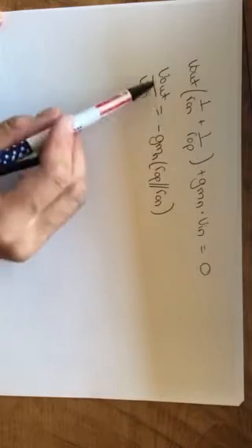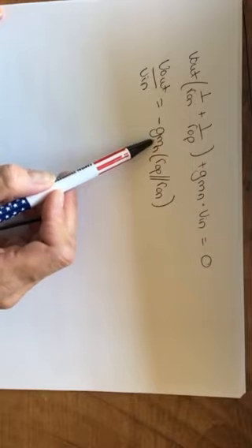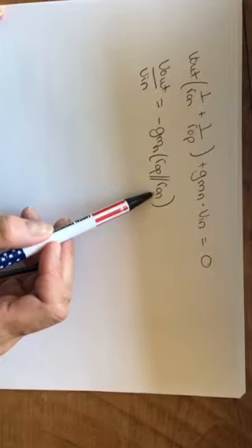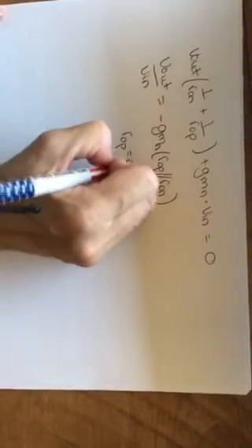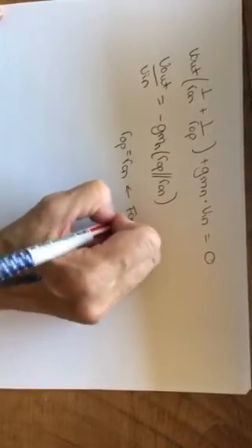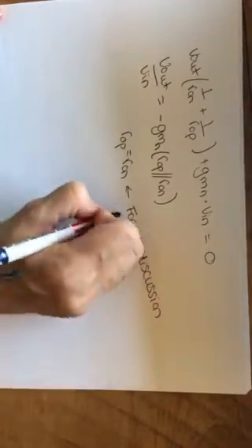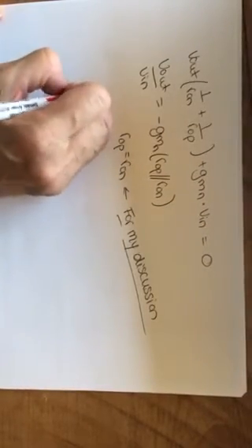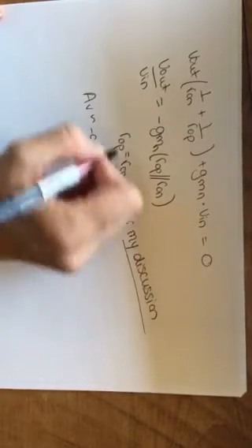So you can see, the small signal voltage gain depends on the gm of the NMOS device, not the PMOS device, that's only the load, and the output resistance of both the PMOS and the NMOS devices, okay? So for the sake of this analysis, let us assume that r0P is equal to r0N. Just for my discussion. This is not the case for you in your analysis, but for my discussion, I want to observe what happens. Let's assume the r0's are equal. Then my voltage gain would be approximately gm N times r0 over 2, where r0 is both of those, right?